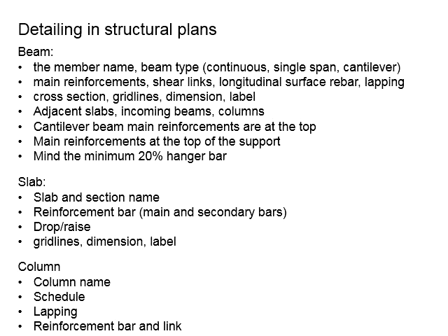Mind the rise and drop, as well as be careful with the arrangement of the reinforcement bar. Clearly indicate the lapping length, as well as the anchorage length at the top of the support. Everything needs to be clearly indicated in the detailing to avoid confusions.